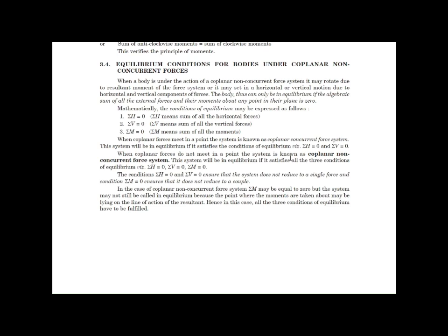But here the forces are coplanar but non-concurrent, which means they are also applying some kind of a moment on the body on which they are acting. So in this context, we will have to take care of the horizontal components, the vertical components, as well as the moments.